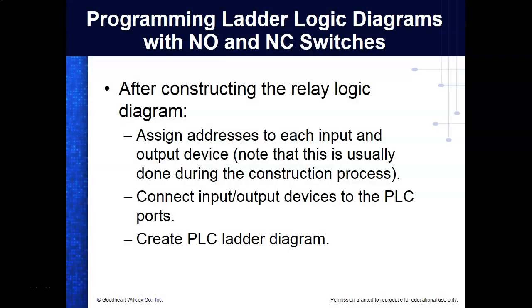After constructing the relay logic, assign addresses to each of the output devices. Note that this is usually done during the construction process. Connect the input-output devices to the PLC port. We usually do that before we even start, and we create the PLC ladder diagram. So I've wired the CPU for you, and in PLC 2, we'll let you wire that PLC up to this edge trainer, and you'll have to wire the PLC if you take the PLC 2 class.